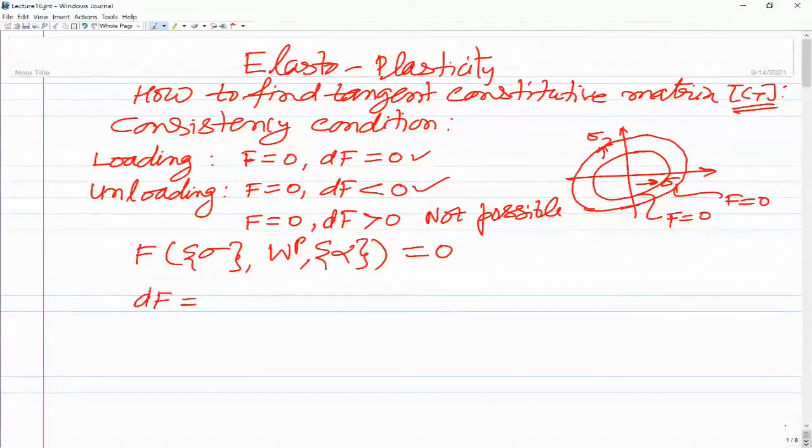Here, aren't we considering some case where the load is constant or something like that? If the load is constant, then in rate independent elastoplasticity, there would be no additional deformation. So you will stay at that state. There has to be a change in load for the change of the state. Sir, how are we saying that dF would be zero in loading? Because the load will increase.